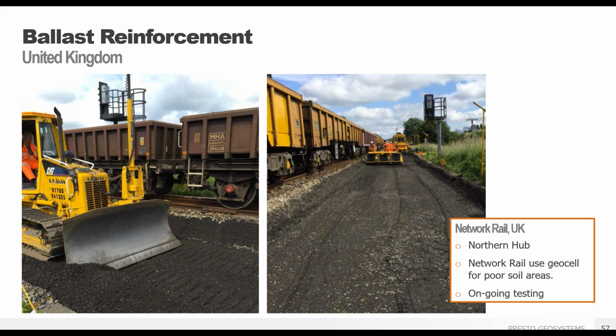So, as a result, the standard required depth of track that they used could have been as high as 1 meter. Which, as Network Rail determined, was really way too expensive to do. So the Network Rail investigation team was pretty much tasked with finding alternative design solutions to reduce that cross-section depth and to lower the cost.